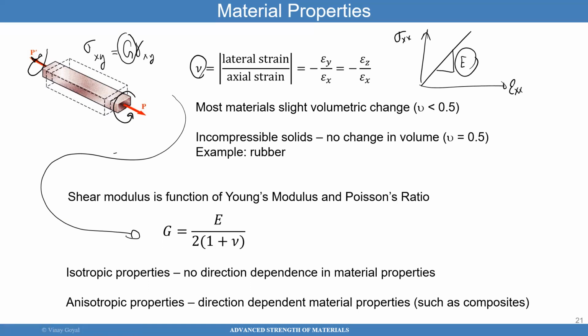And anisotropic is the opposite, where the properties vary dramatically from one direction to another. So Poisson ratio is not a failure quantity. Poisson ratio is a measurement of how much the material contracts in the other directions when you stretch it in one direction. That's all it does. For rubber materials, it is close to 0.5, and for other materials, it tends to be closer to 0.4 to 0.3 and so forth. Okay, so continuing on then,